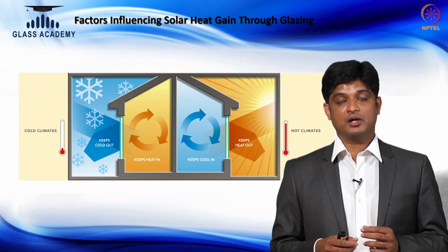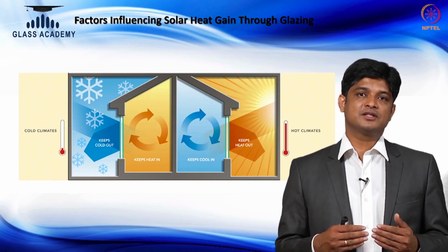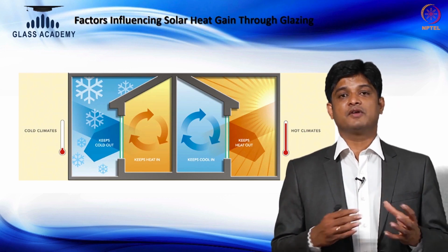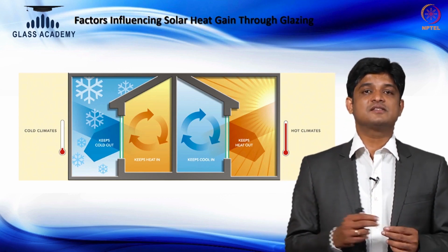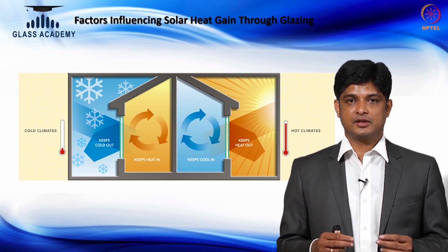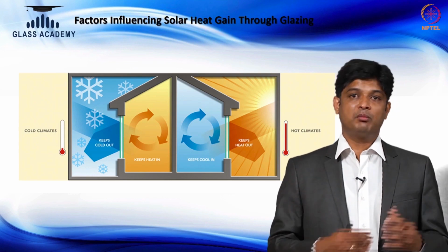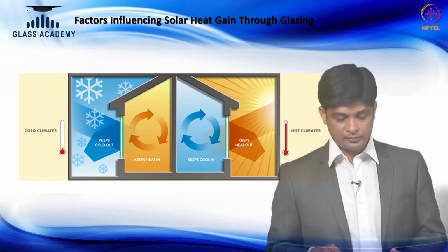Yes, there are options available. In fact, NBC starts with a very clear note saying the glass selection has to be done based on the location. For example, there are different kinds of glasses available in the market. It has to be precisely selected based on the climatic conditions. In fact, ECBC very clearly defines 5 climatic zones, and based on the 5 climatic zones, how the glass selection can happen, which I will take you through.